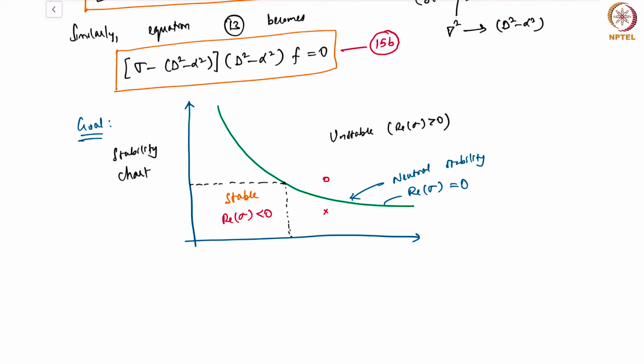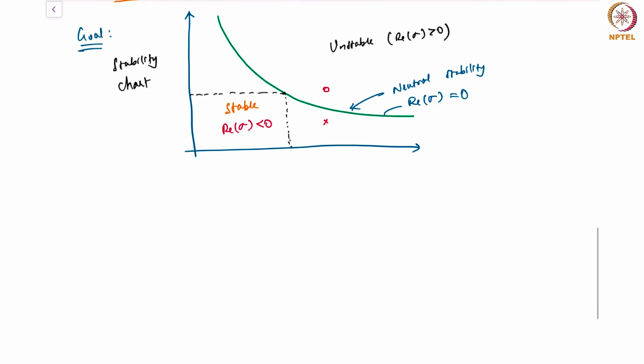But in the Rayleigh-Benard problem, one of the things that can be shown rigorously is that at the marginal or the neutral boundary, the so-called principle of exchange of instabilities is valid. This has been shown by Vidal and Acrivos in 1966, I believe.